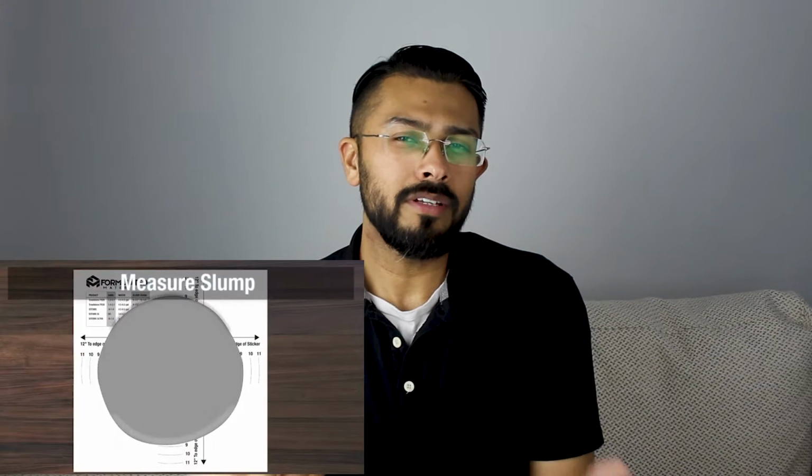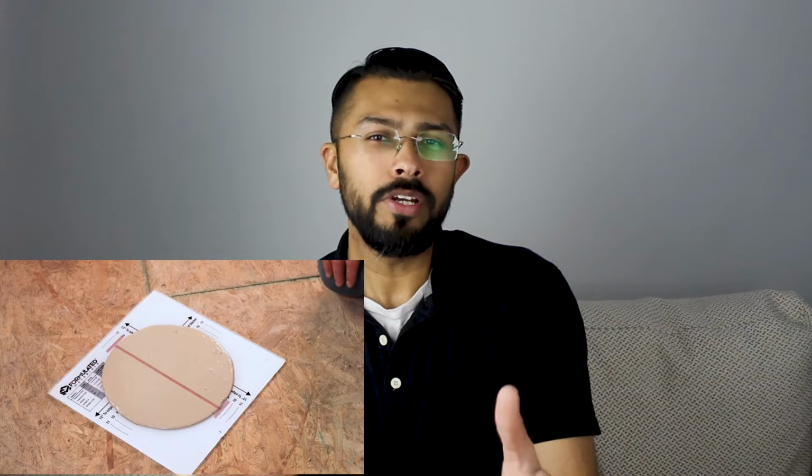The fluidity is defined as the average of the major and minor diameters of the slumped material. It is basically the flow of gypsum material when being transferred from the rubber bowl to the mold after the mixing phase.